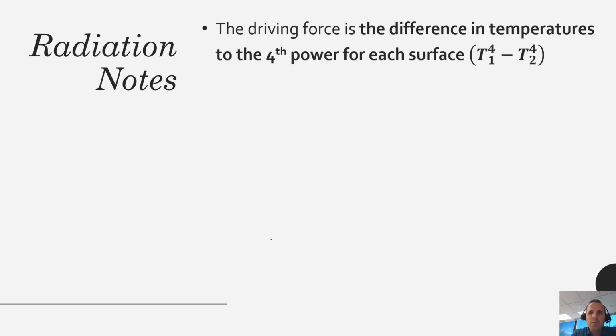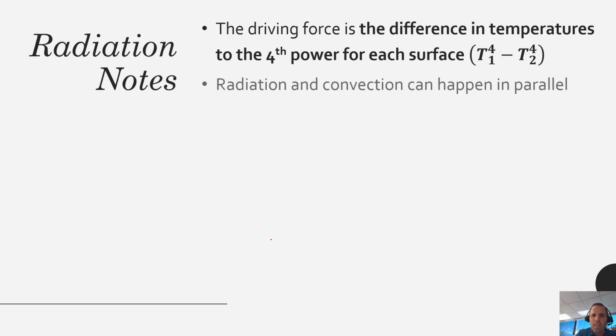Okay, so just some notes on radiation. The driving force is the difference in temperatures to the fourth power for each surface. That driving force will basically be the same even as we get into more complex geometries and even as we get away from that black body assumption.